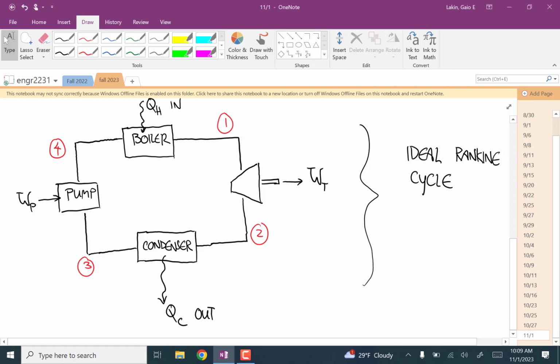And then I guess in this case, it's done by, so you have, I mean, you could turn a turbine with air. So why do we have water instead of air? Because you get a huge difference in pressure by going from liquid water to steam, a huge difference in specific volume. You can do that with air too, but you'd obviously have to get a really low temperature in order to turn the air into liquid.